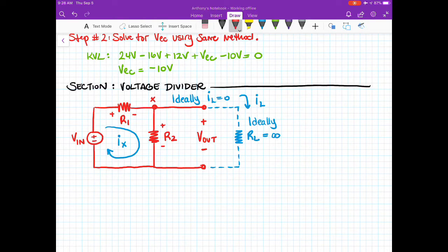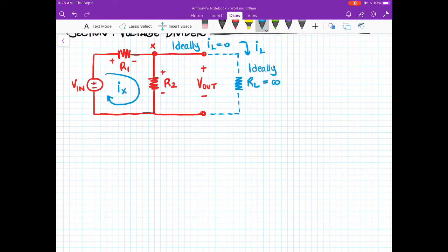All right. So now that we know what the circuit looks like, how does it work? What expression describes its operation? So we can determine how we get the proper relationship between V out and V in. Okay, so it's this. We have V out is equal to R2 over R1 plus R2 times V in. All right, so this is the important expression here.